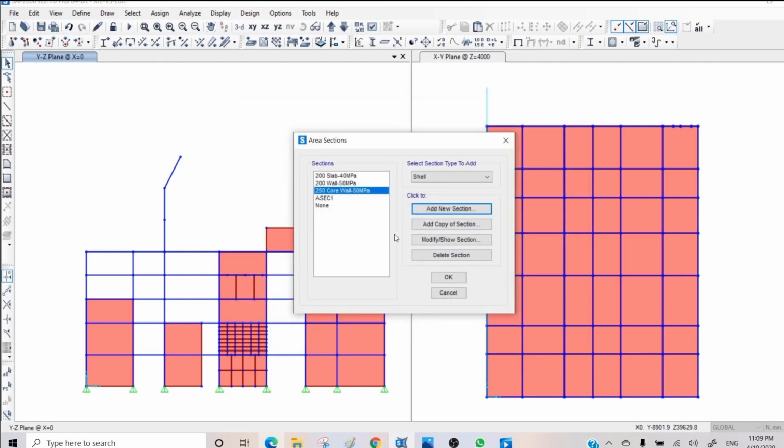If you have, for example, a foundation, where the thickness is more, then those stiffness factors are different, and you may use shell thick. So I leave that one for now, and I will just keep going with the slabs. If I want to have a plate or membrane that I want to use for some one-way slab, for example, one level where I want to have a kind of composite section, and I want to transfer all loads just to the secondary beams.